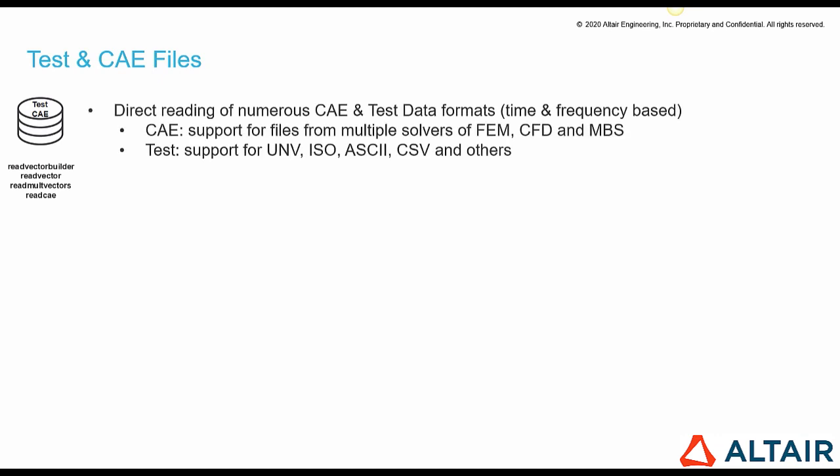Compose allows direct reading of numerous CAE and test data formats, time and frequency based. Regarding CAE, we support files from multiple solvers of finite element method, computational fluid dynamics, and multi-body systems. And regarding tests, we support formats such as UNV, ISO, ASCII, CSV, and others.